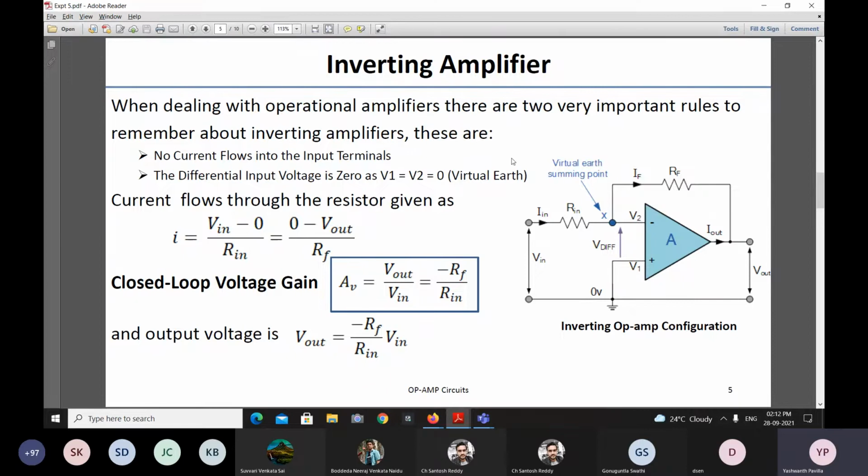In this particular operation in inverting and non-inverting amplifiers, we are controlling the gain and making it stable. In order to do that, we have to connect the feedback to the negative terminal. So here we have connected the feedback to the negative terminal of this device, so that ultimately it can give us a stable and controllable gain. So gain is nothing but the improvement in the amplification, right?